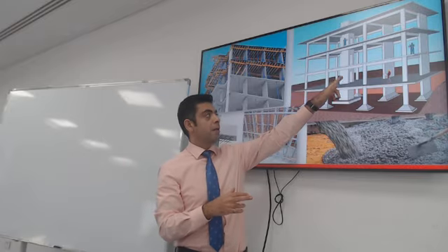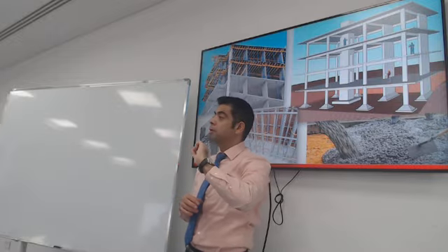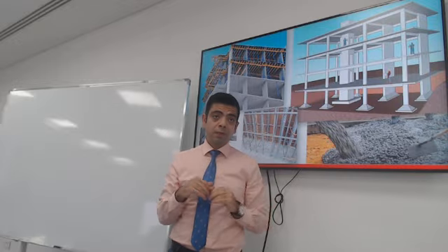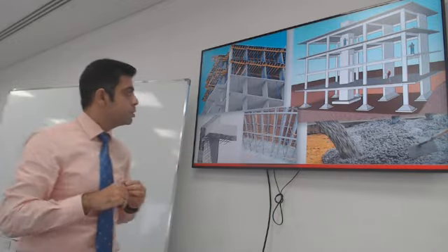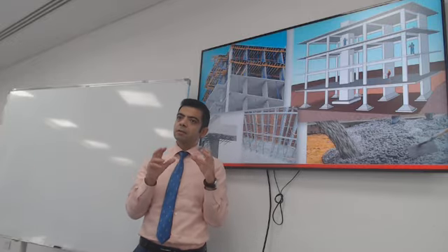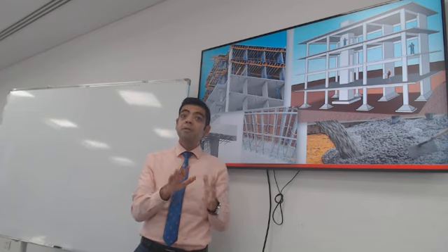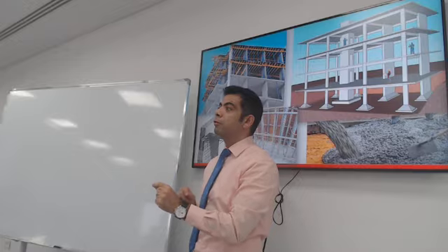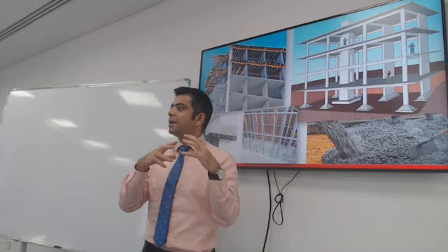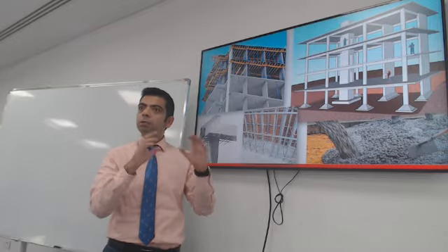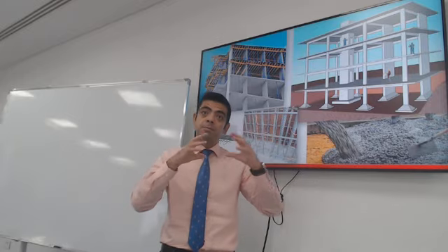And you also look at the walls, which most probably you're going to use to resist lateral loads, like wind and earthquakes. So I need you to understand that design of reinforced concrete, this is a material. It's called reinforced concrete. It's different than just concrete. That's why there is such a thing as minimum reinforcement. If you're designing reinforced concrete, you have to put at least a minimum amount of reinforcement regardless of the load. Obviously, if the load is bigger, then you need to increase the reinforcement.